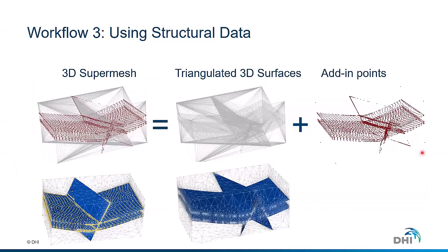So what is this 3D structure mesh? Well, it's a definition of a set of surfaces. These surfaces preferentially will be triangulated surfaces. The surfaces are defined by edges, the edges are defined by points, and everything has to fit perfectly.